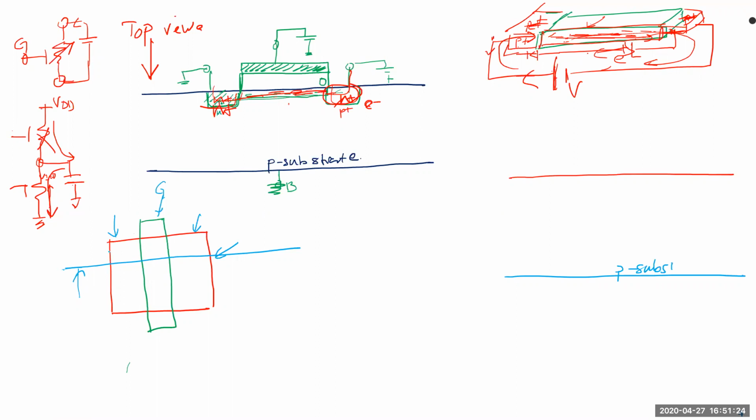So if I cut it, first they find out how much area I need for the ion implant. What they will do is take this area and AND it with this area, and then do the ion implant to do the threshold adjustment. And then take the gate area, put the oxide here, and then they'll put what's called polycrystalline silicon, usually called poly.